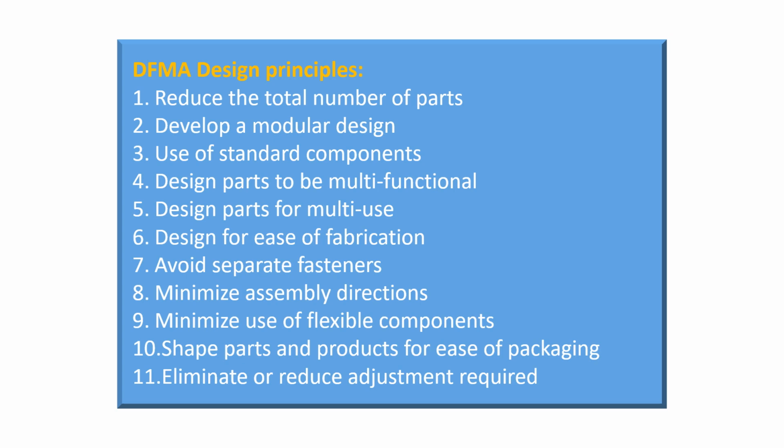7. Design the product for foolproof installation. The configuration should be unambiguous. The components should be designed so that they can be assembled in only one way. Special geometrical features sometimes need to be added to components to prevent misassembly.